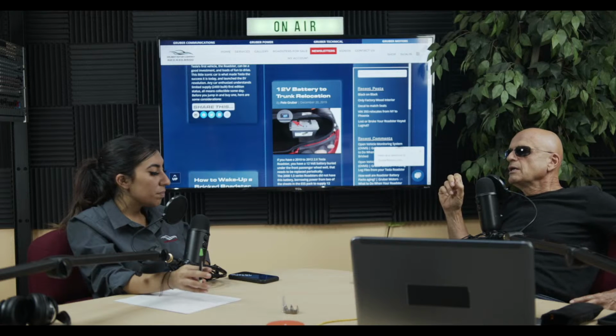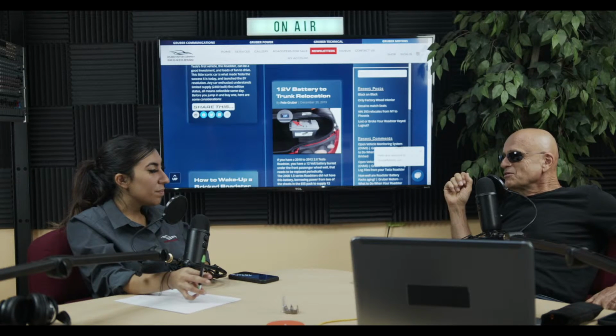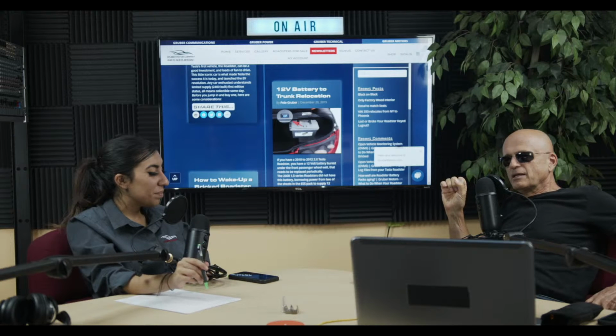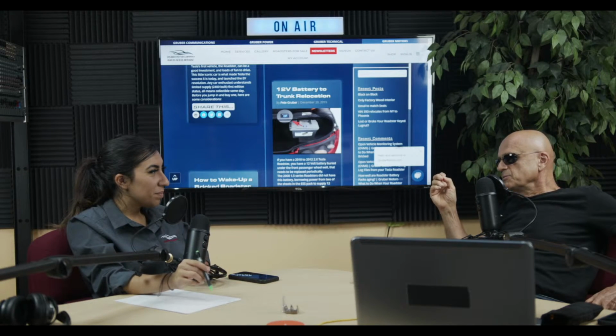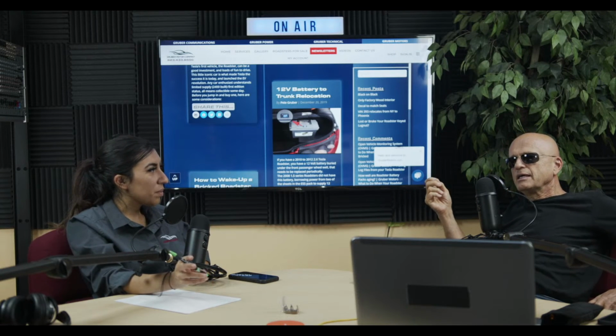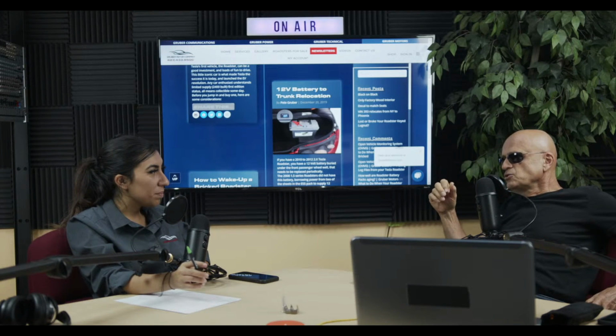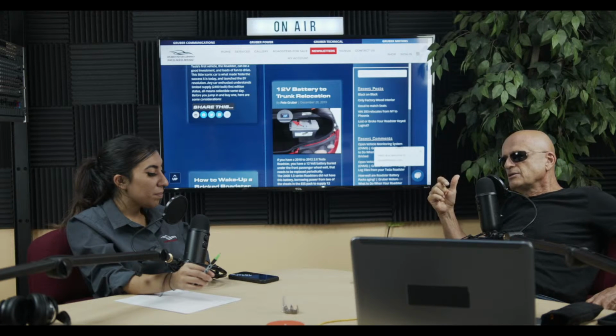So they finally realized to do this properly, we really need to install a 12-volt battery in the Roadster. But they've used up all the real estate. So they found a place underneath the front passenger fender behind the wheel well to place a little motorcycle battery. And like all 12-volt batteries, they need to be replaced. This is an absorbent glass mat battery, which although maintenance-free, in other words, you don't have to pour acid into it, has a lifespan. And 2 years is typical. So every time you needed your 12-volt battery replaced, you had to go to a service center, unless you were really adventurous and did this yourself, and spend a few hundred dollars to have this little motorcycle battery replaced.